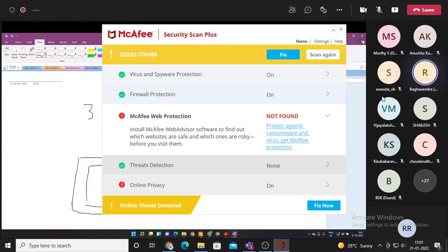In a USRP, you can actually take out a daughter board and replace it with another daughter board. The motherboard is the main unit of the USRP, which we usually do not take out. If you take it out, it's the same as replacing it with a different USRP. The daughter board, whereas, we can actually replace.